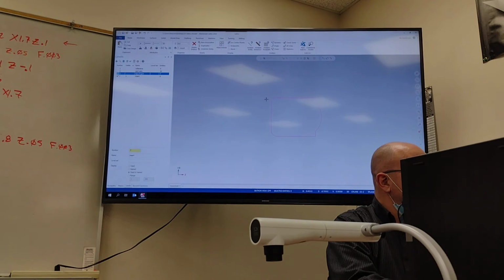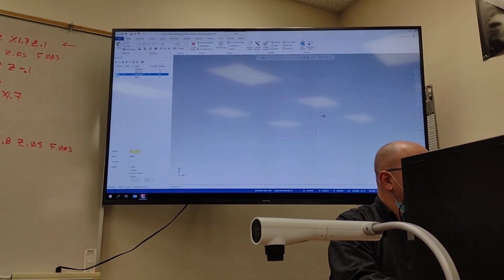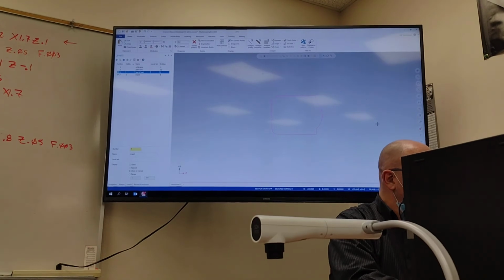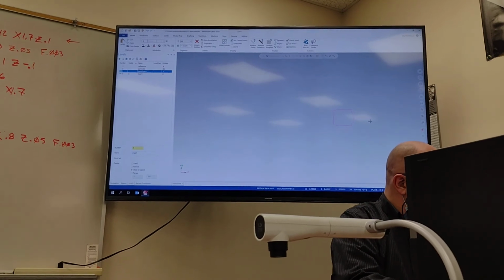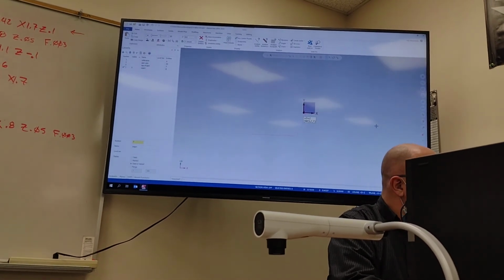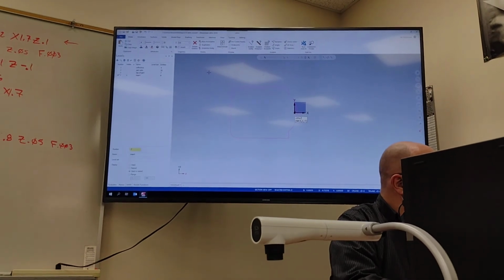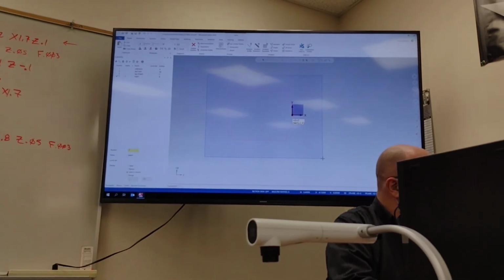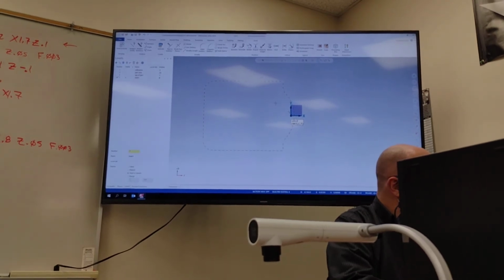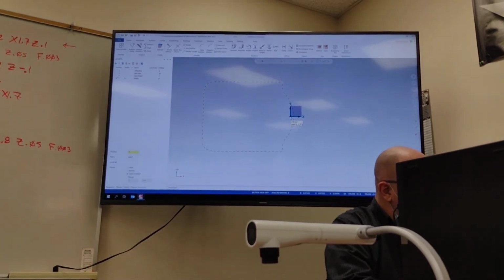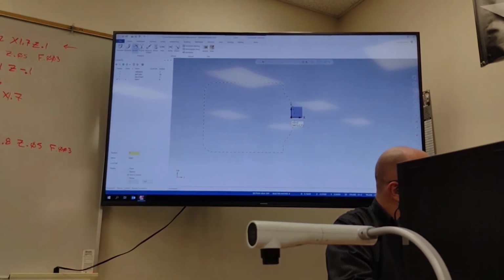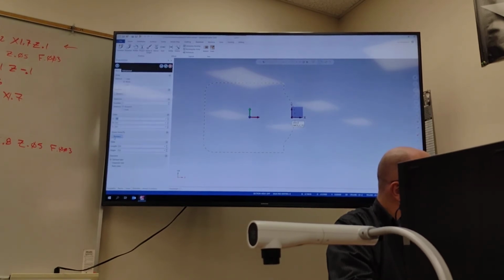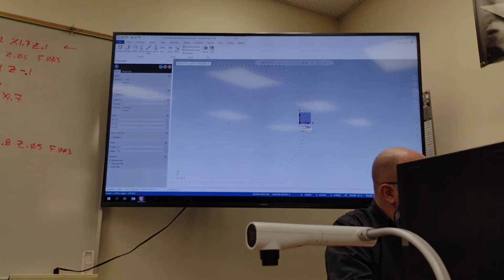And when you actually make this portion of it, let's go ahead and do that. Now we're going to make a toolpath for this portion of it. I'm going to move this back so the tip of my part is right here at Z0 for programming purposes. Transform, translate, from, I'll click in there, click on my origin, green check.